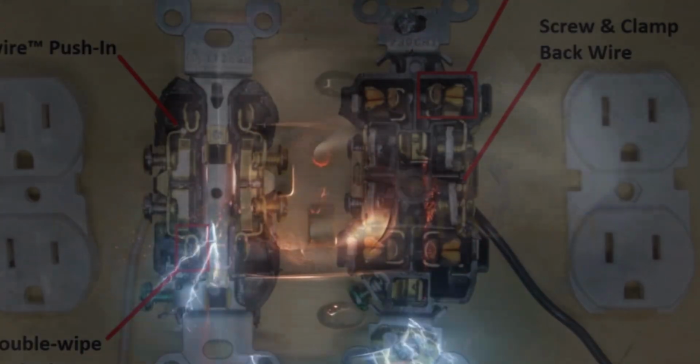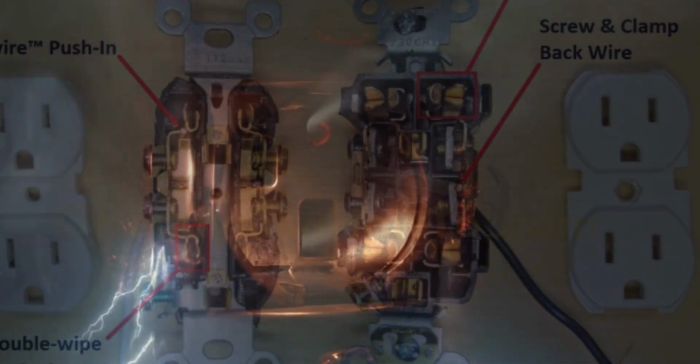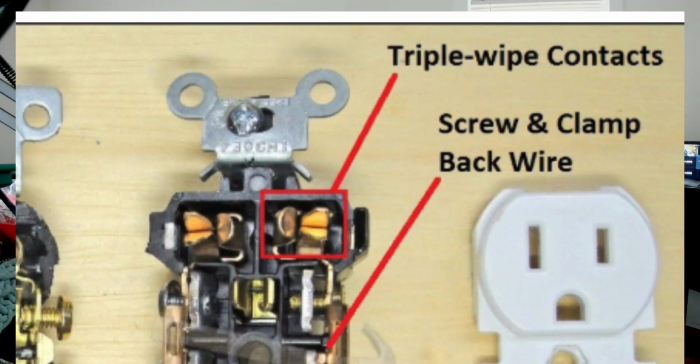And she was complaining about the outlets not working or working sometimes. Well, I pulled out the outlet and it literally broke apart in my hands. The screw stayed on there, but it broke apart in my hands because the heat from the ampacity going through the outlet was so hot. That little piece of metal in those little holes was barely touching, and over time was starting to slowly build heat.